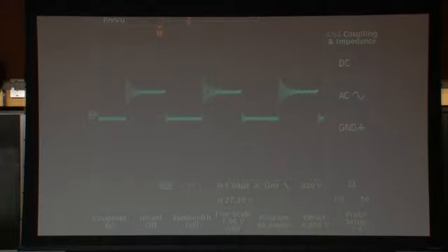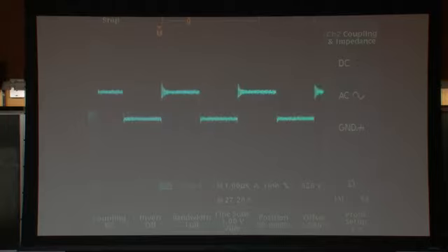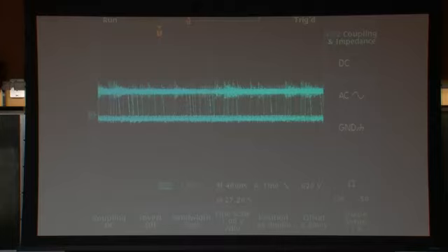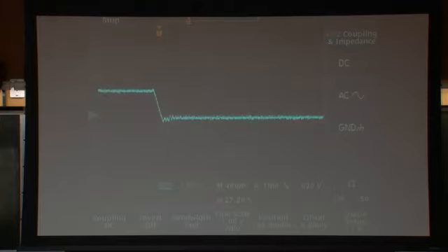We're going to move the capacitor closer to the switch. We're going to have a bad switching loop, but smaller area. So we're going to reduce the capacitance here. We're going to improve one aspect of that. Sorry, I just changed everything, but okay, that should be good.